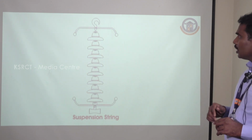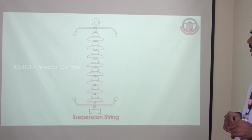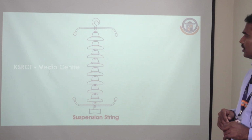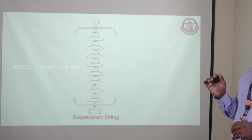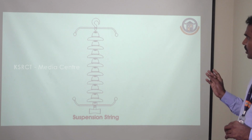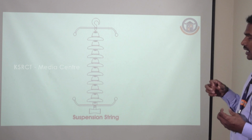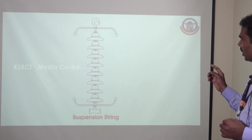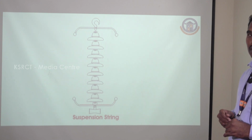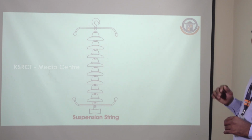We are having the cross arm in the top portion, and the bottom portion also we are having a cross arm. In the bottom portion we are going to fix the conductor, and the top portion we are going to fix to the tower. In between top to bottom there will be a metal link for each disc, connected to every one. The suspension string insulator has a problem of voltage in the bottom of the disc being much higher than the top portion of the disc.